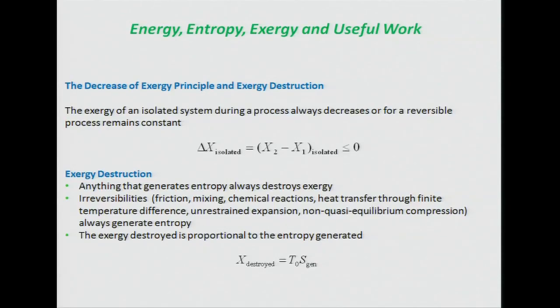So, a couple of principles come out of this. If you have an isolated system, so I don't put any mass into it, I don't do any work on it, and I don't supply any heat to it, then the change in the exergy of an isolated system when a process occurs is either equal to 0 if that process is reversible, or it's less than 0 if there are irreversibilities in the system, which in a real system would happen. And that exergy is destroyed.